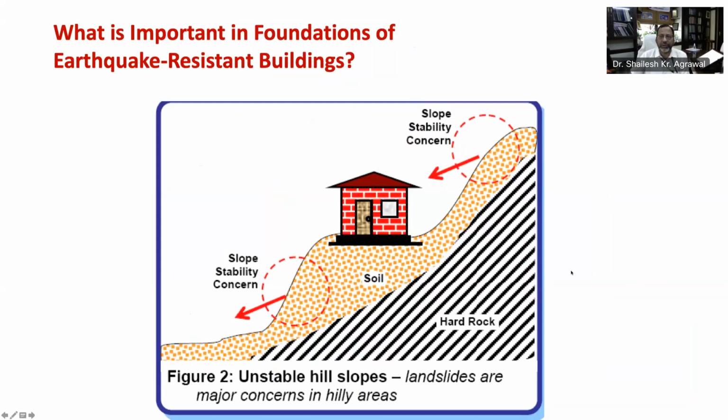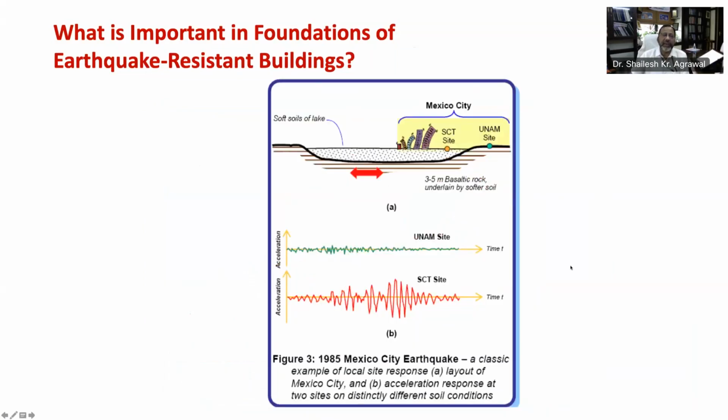Now let's understand through this figure what is the effect of ground shaking on building. Even if local strata underneath a proposed structure is stable, ground shaking may be modified when earthquake waves propagate through the soil overlying rock layers. This phenomenon is referred to as site effect. Means even when shaking at the base rock is moderate, the motion at the site may be amplified by soil above rock, and this needs to be accounted for in the design.